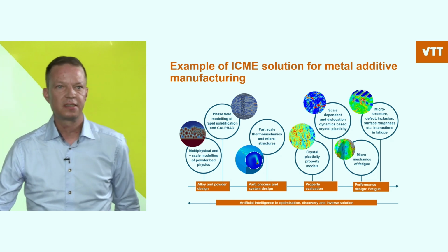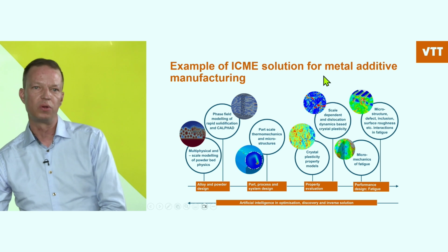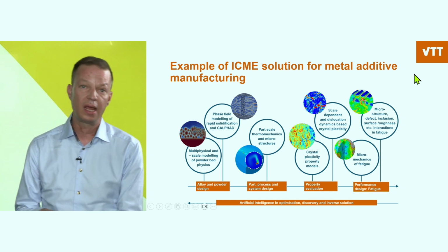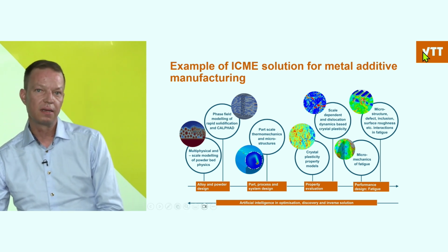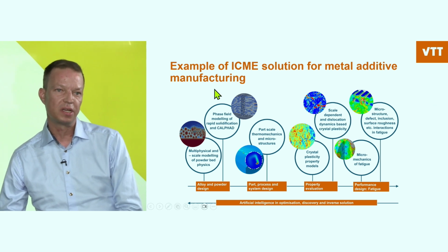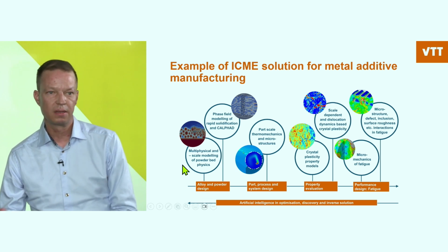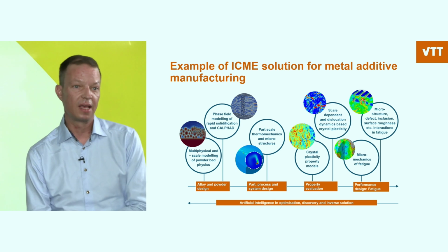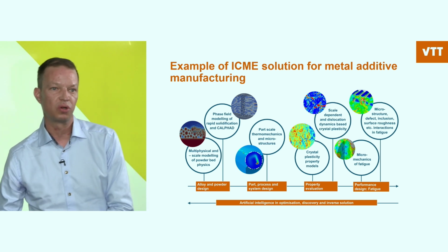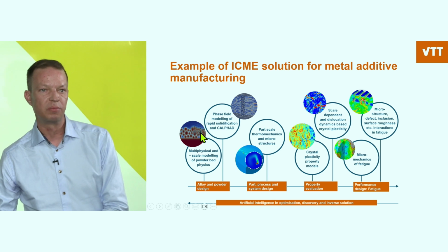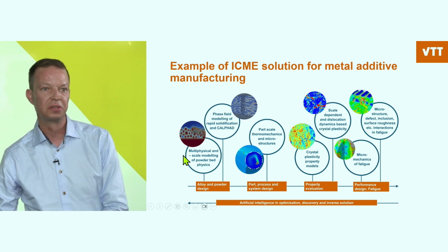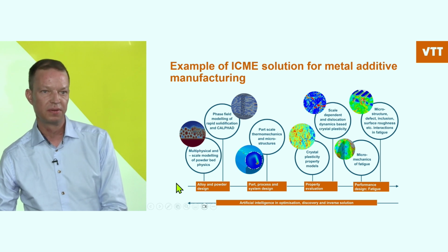One example of the techniques that we use is metal additive manufacturing, meaning 3D printing. This could be any manufacturing technique, but we can go basically computationally throughout the whole thing. So we can design the alloy with the smaller scale methods like DFT, MD, Monte Carlo methods, and so forth. We can model the laser material interaction over here, how it melts, what vaporizes and how much. So it's a multi-physical and multi-scale modeling of the powder bed physics.